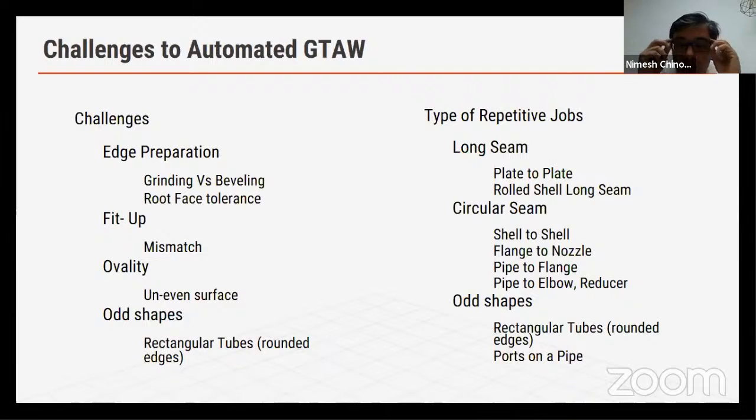If you're doing, say, a shell of about 4 mm thick stainless steel, or a 5 mm thick one, but 2 meters or 3 meters in diameter, the minute you roll the shell it will try to self-fold downwards because of the ovality created or the load. You may use spiders to maintain the ID, or you may have ovalities.